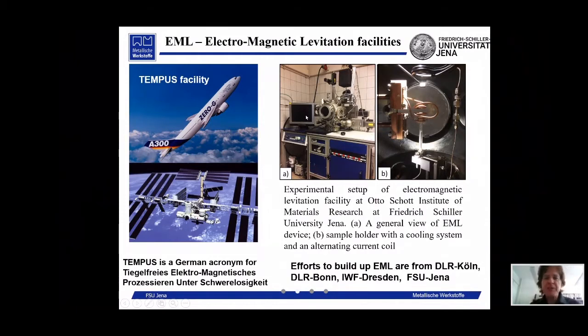from the high-speed camera. The high-speed camera setting depends on the alloys. For instance, in glass-forming alloys, the kinetics of the propagating recalescence front is much lower. Kinetics is much more sluggish than in normal, for instance, substitutional alloys. Therefore, we adjust the camera to the concrete alloy, but normally